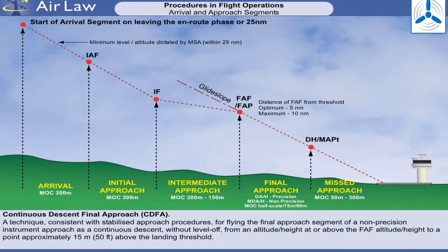Research has shown that non-precision approaches carry an increased risk of controlled flight into terrain, CFIT. The CDFA allows constant supervision of speed, power, configuration, descent path and height, an ideal situation for managing the final stages of approach of an airliner and thereby avoiding CFIT.